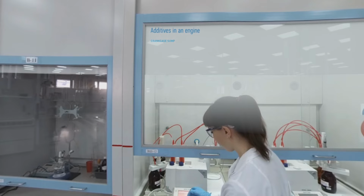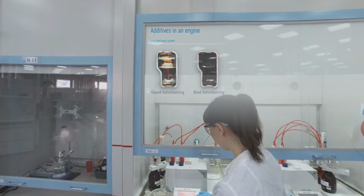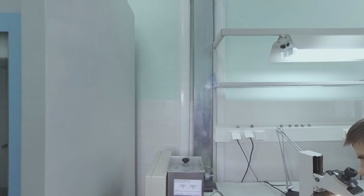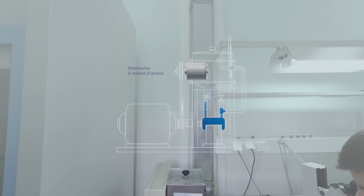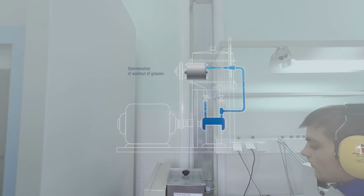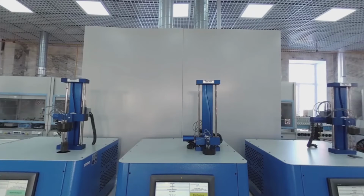Moreover, a higher total base number enhances the protection ability of oil against deposits on the engine parts. Here, the ability of grease to remain confined within a friction unit under impact of water is assessed. A standard bearing is filled with lubricant and is flushed using a hot water jet for 1 hour. The water washout stability of the grease is assessed by the remaining amount in the bearing joint.